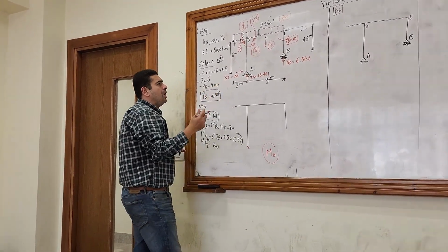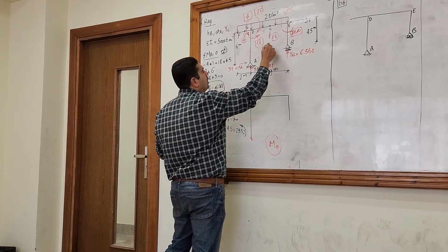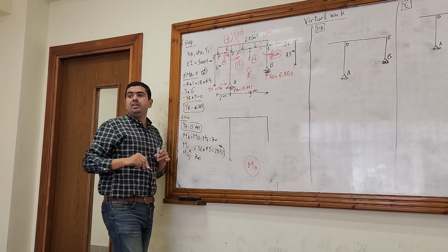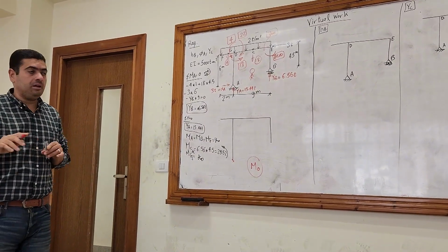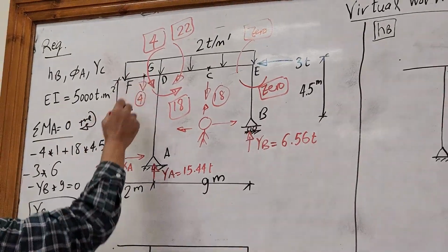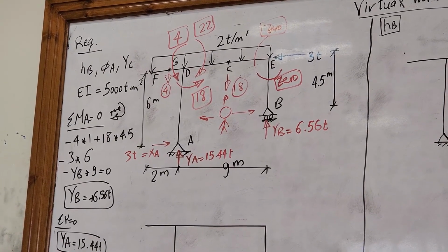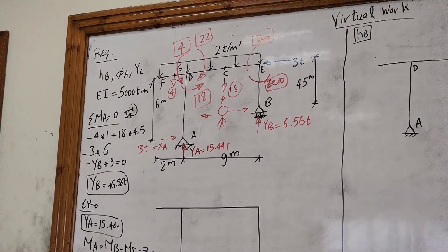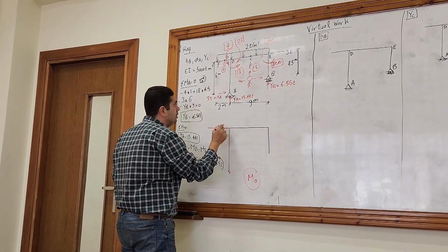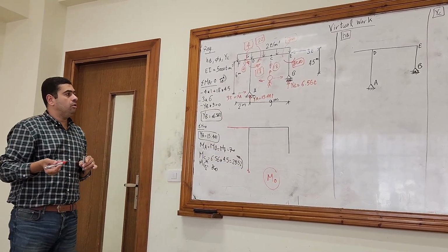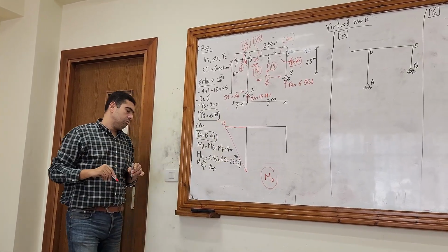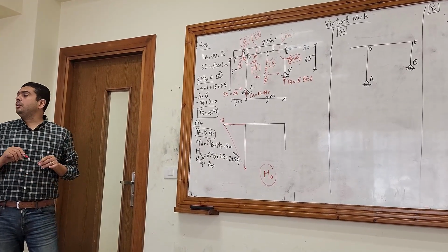In structure 1, I don't know how you got this. I used to tell my students, pretend that you are inside the frame. Pretend that you are inside the frame. So look at these members like this. So the member DA, when you locate the moment 18, you can easily know that it's upwards when you are looking from this side, right? So locate it upwards like this. And no any distributed load on the member, so you can easily draw a straight line like this.